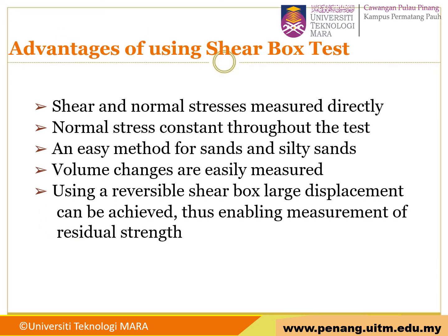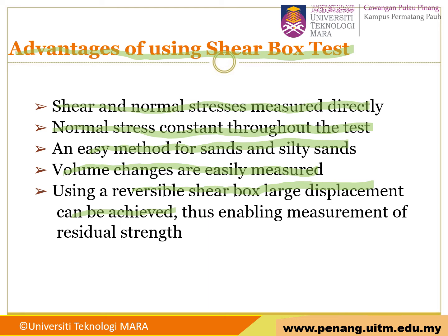Alright, so now we look at the advantages of using the shear box test. First, shear and normal stresses are measured directly. Number 2, normal stress is constant throughout the test. It is also an easy method for sand and silty sand. The volume changes are easily measured, and using a reversible shear box, large displacement can be achieved, thus enabling measurement of residual strength.